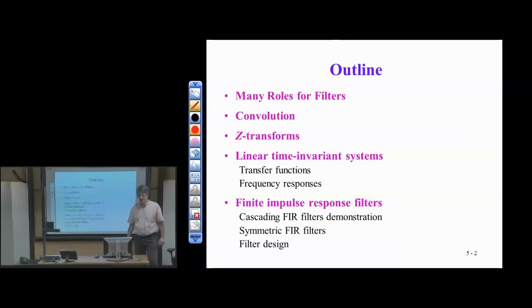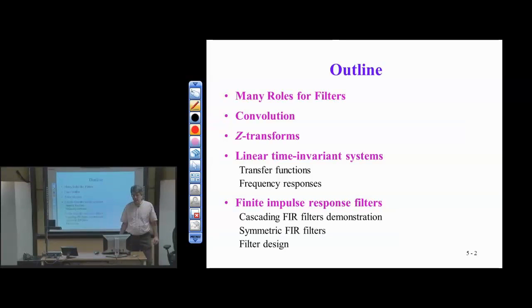response of the filter. We've talked about Z-transforms, which give us another analysis tool to analyze the function or properties of a linear time invariant system. The Z-transform of the impulse response is the transfer function. This allows us to know what happens in a generalized transform domain from the input of the filter to the output of the filter. Talked about frequency responses of LTI systems, and certainly a good example of this is for filters. That is to say, in this class, a filter is a bounded input, bounded output, stable, linear time invariant